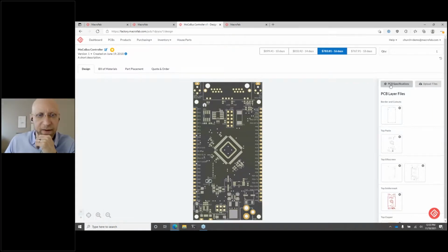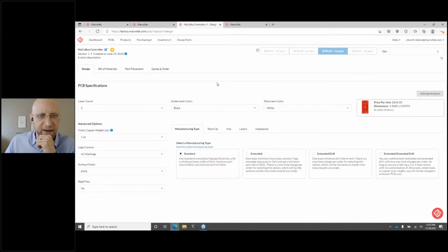Okay. And then, one of the questions I have gotten often in the past is, how do I control the different parameters for my design? So we offer 4 different sets of DRC rules that we can apply here. And each one will actually change the cost a little bit. It'll actually show you, as I do that, we can go, for example, from a 5 mil minimum trace width to a 3 mil.